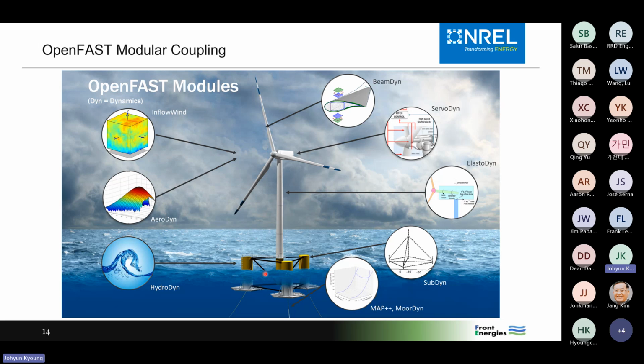Yes. Okay. And so that means if you use Subdyne with these 3 rigid bodies and the flexibility, you can eventually calculate the wet natural modes of the tower, if you put everything together. Absolutely. Okay. So there is an option to calculate this natural frequency.